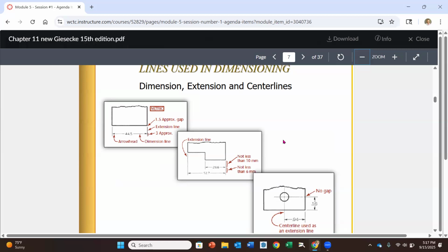When we are making them using tooling in the manufacturing environment, the spindle center we can identify, and we know where that is in space. So we use that spindle center or the center line of a cylindrical feature if we're making a hole, for instance, or a bore, and that is identifiable as far as location on your machine tool, and we want to also identify that on our drawing. So center lines are going to be used for that purpose.